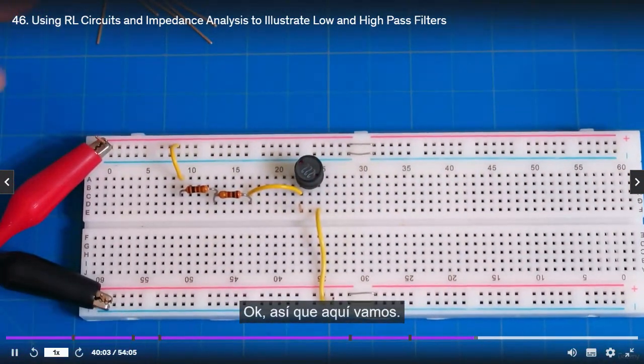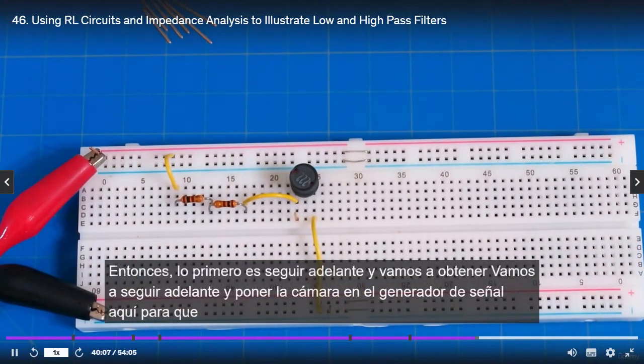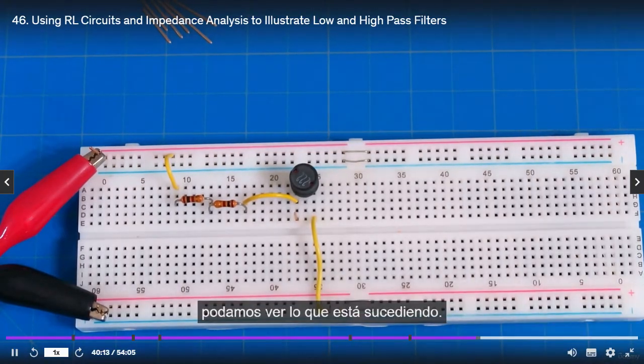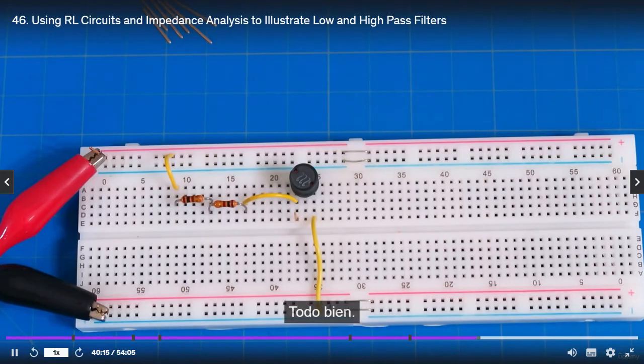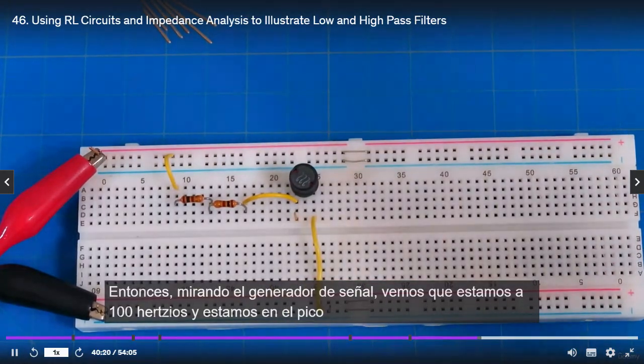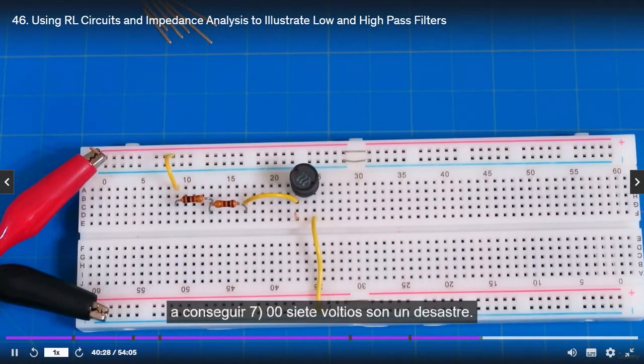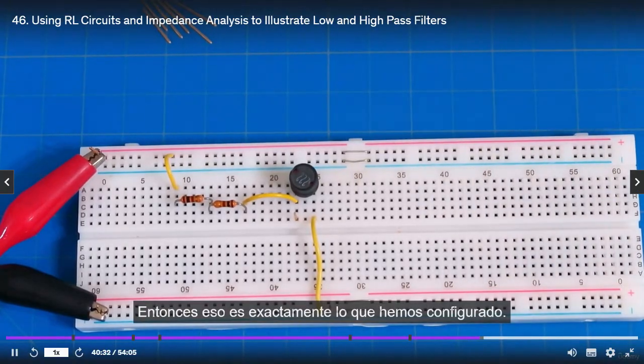Okay, so here we go. The first thing is, let's get the camera on the signal generator here so we can see what's going on. Looking at the signal generator, you see we're at 100 hertz and 20 volts peak to peak, which if I split this, it's 10 volts and minus 10 volts, all right? So we're going to get that 7.07 volts RMS. That's exactly what we've got set up.